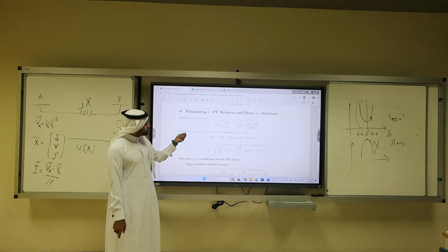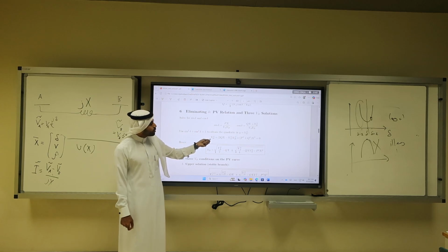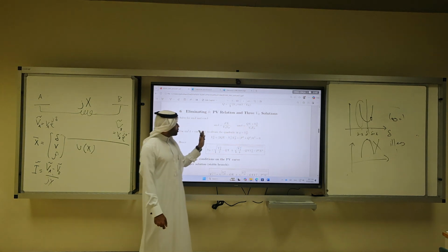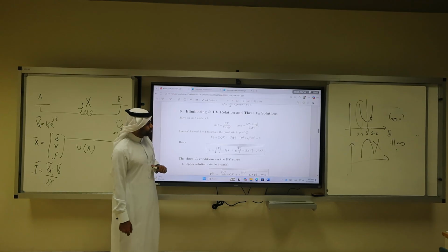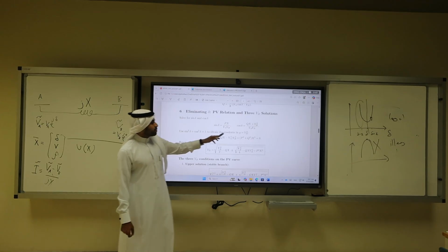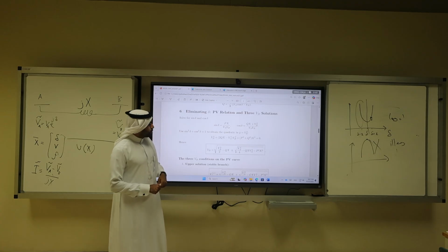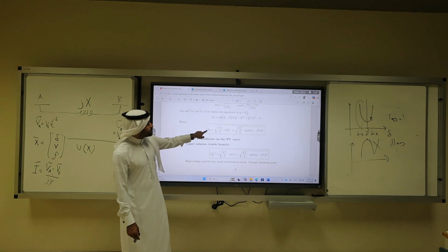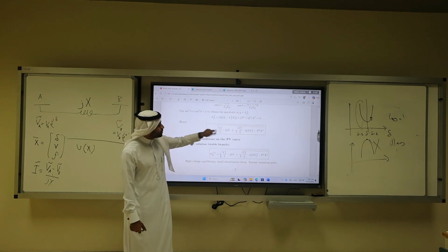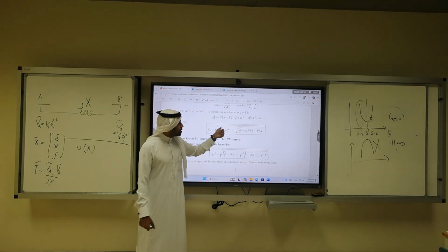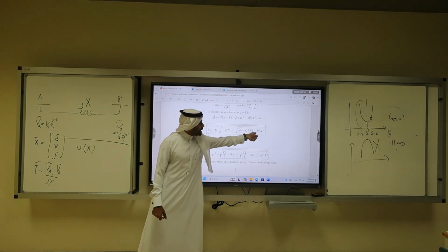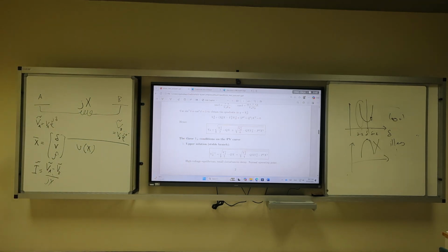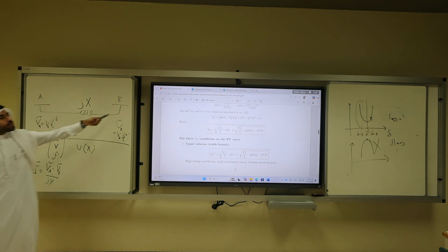How did they do it? They used this trigonometric identity, sine squared plus cosine squared equals 1. This is the sine, this is the cosine, equate them to 1. Then you should have this number. And y is VB squared. So once you do the equation, we can have this equation. VB equals, I can write it as a function of VA magnitude, not phasor, Q, reactance, P, and VA. So by knowing the power flow in the system, I can predict the voltage level here.